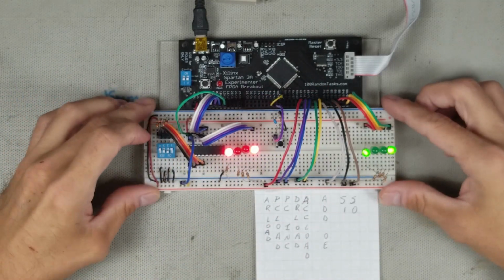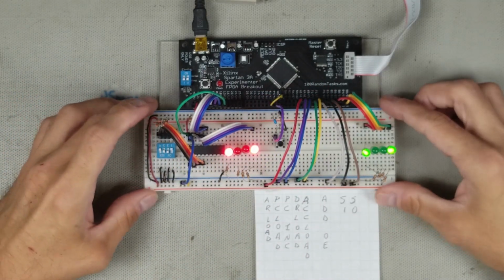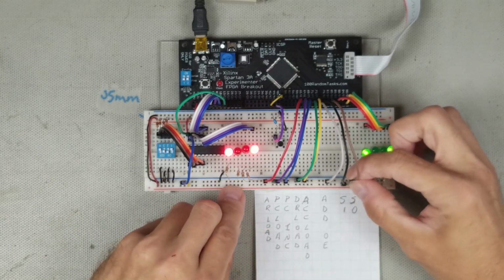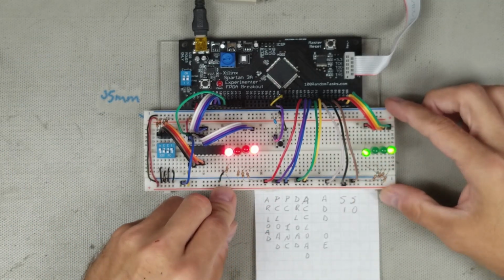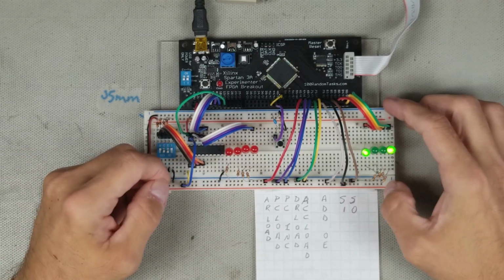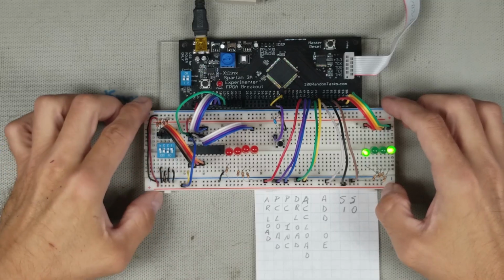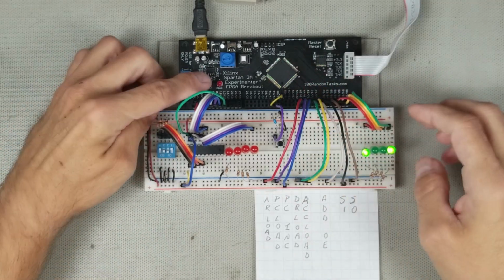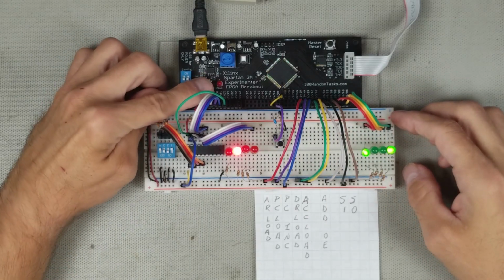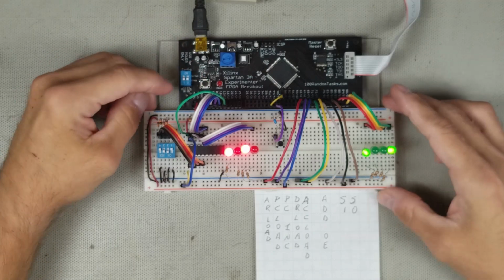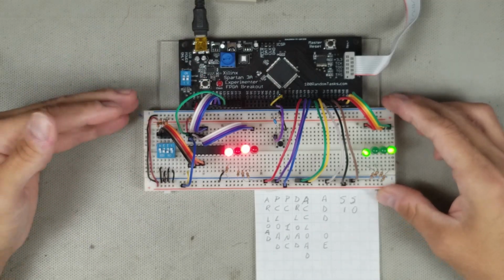Let's have a look at the program counter. I'll set the AR load back to 0 and set the select lines to 10, which is the MUX address for the program counter, and the read-write to write. Now it shows 0, but if I set the PC increment line high and cycle the clock, it should start counting. Perfect.